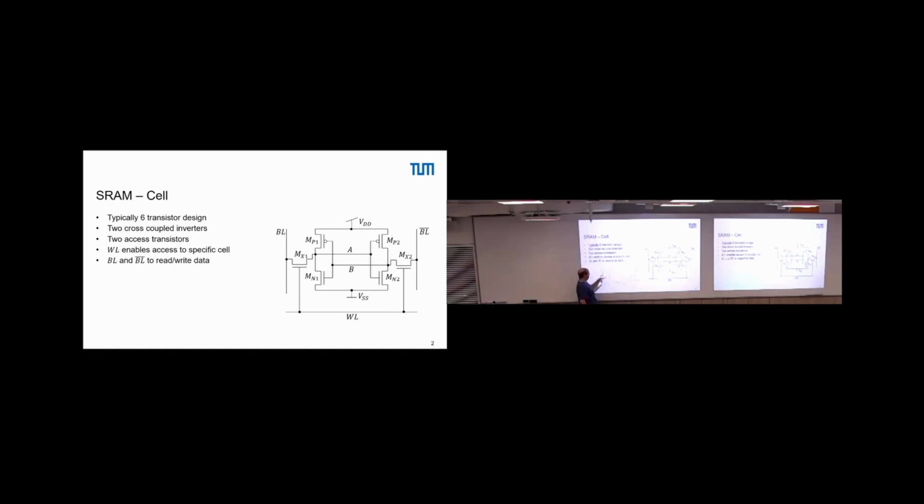If we increase this, at some point the NMOS transistor starts conducting. So the inner node is no longer at VDD, but these are two resistors more or less, right? And the more we go in the direction of VDD, the lower the resistance of the lower transistor and the higher the resistance of the upper transistor, right? Where do I lose you?